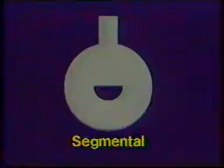An eccentric bore plate can be used for processed liquids that contain some solids. The plate can be positioned with the bore at the bottom of the pipe to allow the solids to pass through the orifice plate. Another orifice plate that can be used when solids are present in the flow is this segmental plate. It can handle thin slurries, but its accuracy is less reliable.